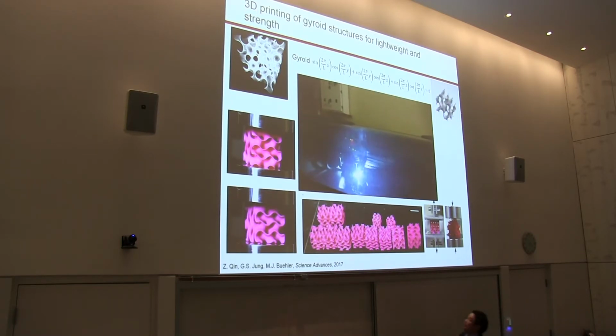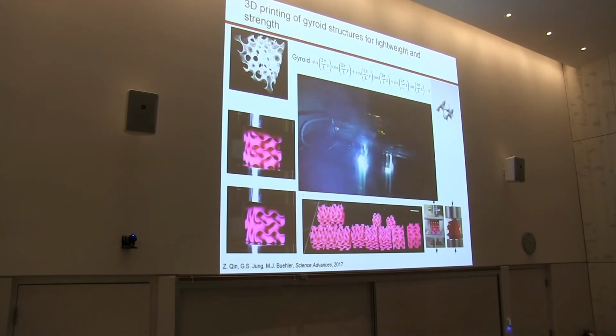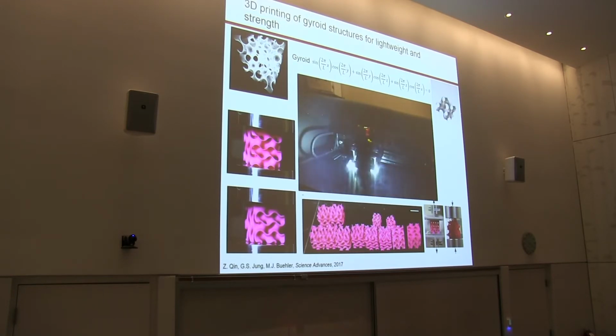Like you can see here, those structures have different wall thicknesses that define different material densities for those porous materials. And then I apply mechanical tests. These two quick movies show you the deformation process for two different designs. The first one is a structure composed of a very thin layer of material. The second one is composed of a very thick layer.